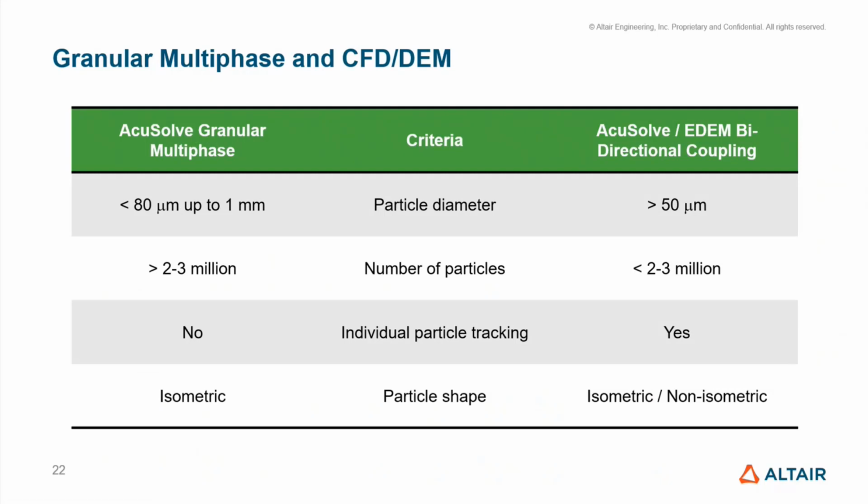So another question you might have is, how does granular multiphase compare to AcuSolve EDEM coupling? Well, the two complement each other, only overlapping in a few areas of simulation criteria. Here are some guidelines to help you understand when to use one versus the other. First, particle size. If your particle size is less than 80 microns, a dispersed method may be the way to go. If less than 50 microns, then you would definitely want to go with a dispersed method.